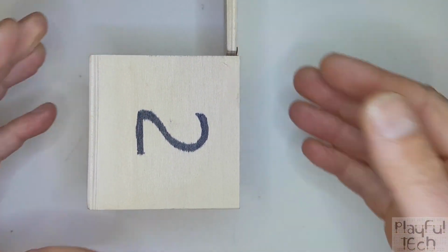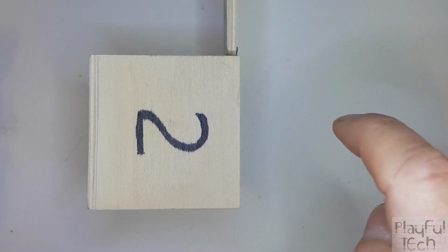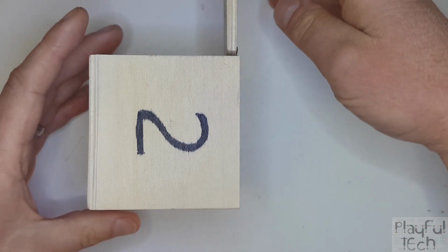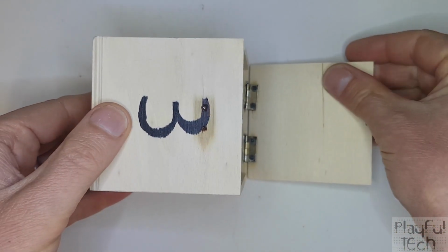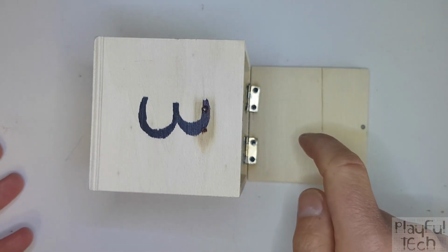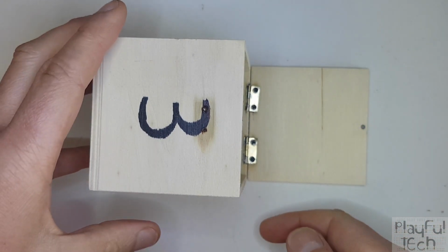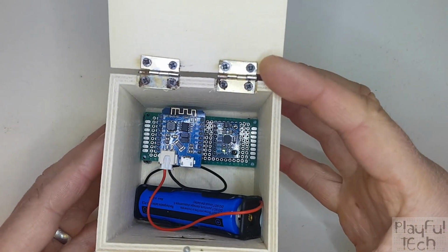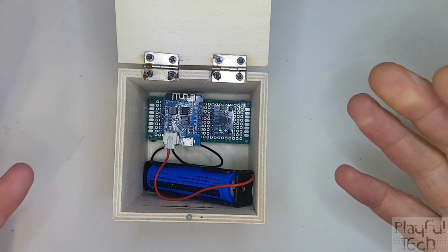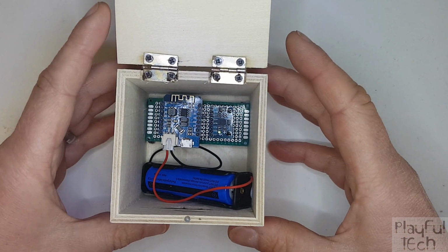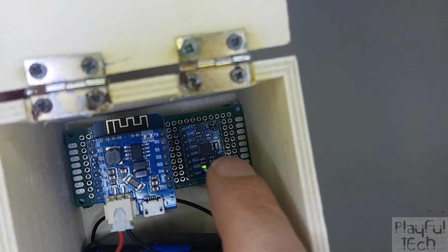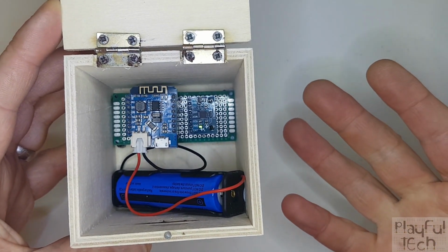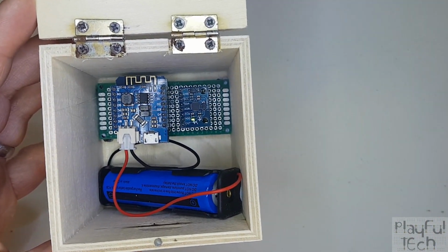If we have the box on this side, obviously the force of gravity is still pointing in the same direction, which is straight down, but now it's acting through the x-axis of the chip. And if we have the cube this way up instead, now it's acting through the y-axis of the chip. So even though we don't have any external forces jiggling the box around like that, the accelerometer will still be used to detect which way the box is up by these axes as marked here, and working out which one of those axes is experiencing the constant acceleration due to gravity.